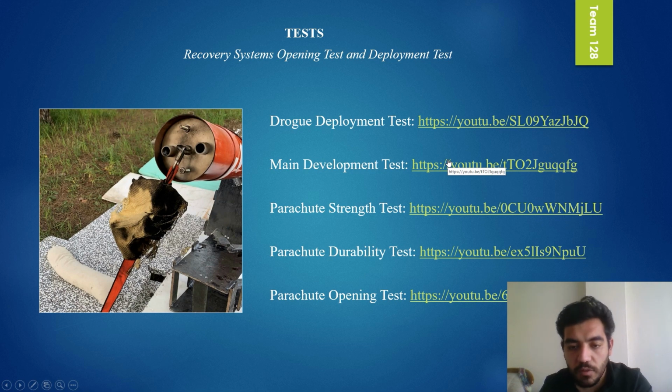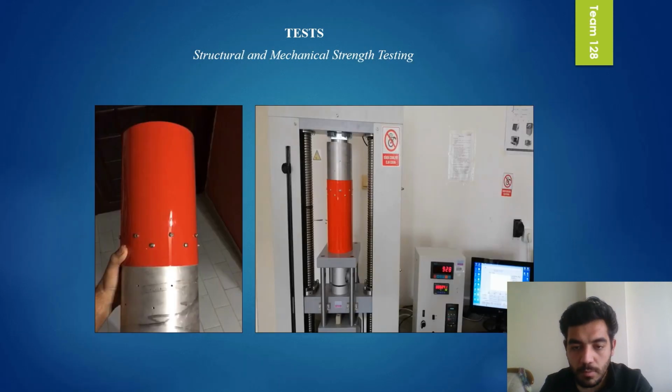An explosion with enough power to open the nose cone is created at this point and at the desired altitude. The mechanism and the materials used are designed not to damage the structure, cables, or shock cords inside the rocket. In the pressure test for the bulkhead, it has been observed that it can withstand more than 910 kg of load. The expected maximum load during flight is 470 kg, which gives us a factor of safety of nearly 2.